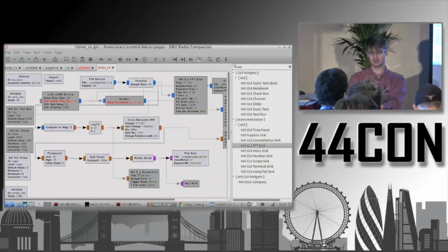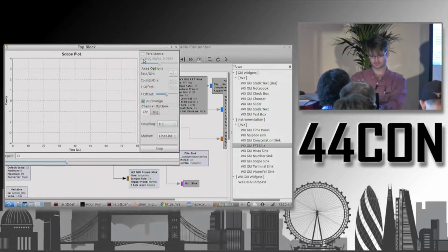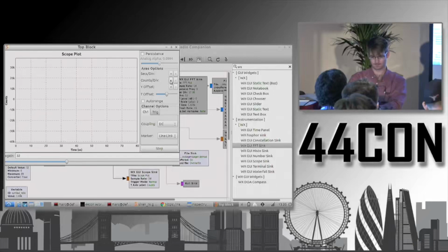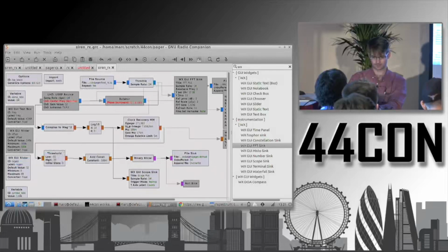I'm changing the sample rate here to the sample rate variable because we're before the clock recovery block. So data's flowing at 1 megasample per second up until this block, and then it's flowing at 3.69 kilosamples per second after that block. This is odd.